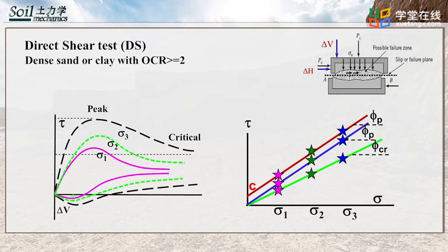During shear, we can generally see two kinds of shear behavior: shearing contraction and shearing expansion. Shearing expansion is a shear behavior showed increasing volume under increasing shear displacement. It can be seen that the tested soil showed shearing contraction first, followed by shearing expansion.